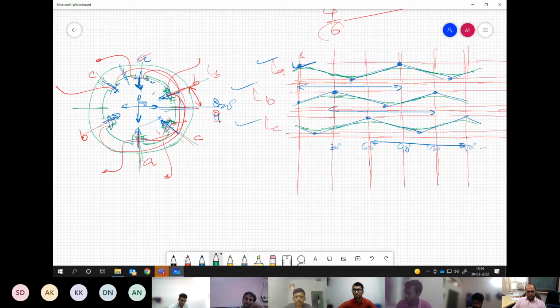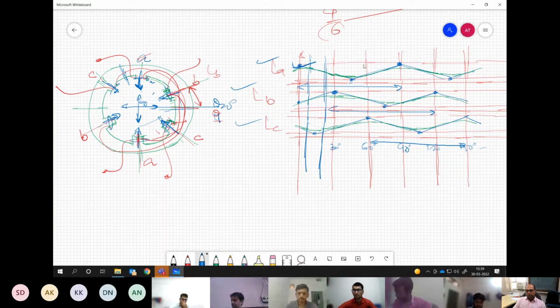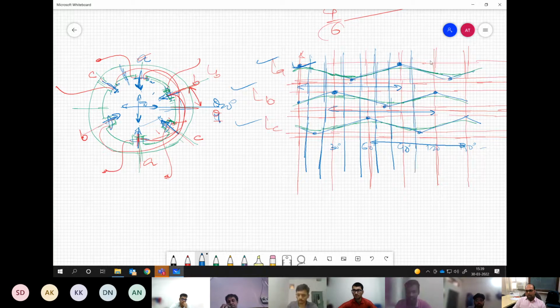So if you see practically, you will have only this middle of this phase where you can apply any current, because that is where you will have a linear dL/dθ for any phase. Let us say for A or B or C, that will come in sequence. This is the zone where one of the phases will be linear. Now which one we have to apply depends on which one is giving me positive dL/dθ, or negative dL/dθ if I want to apply negative torque.